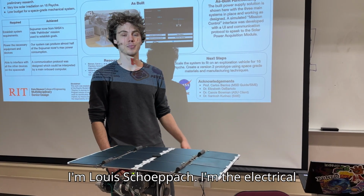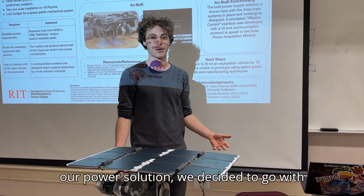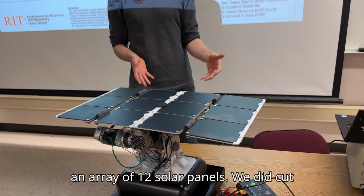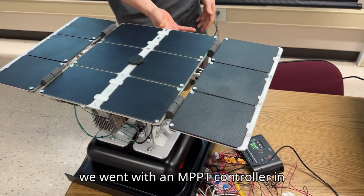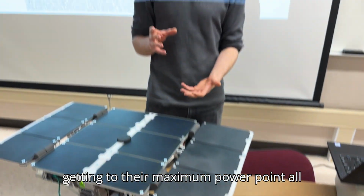Hi, I'm Schoeppach. I'm the electrical engineer on Psyche Mission 2. For our power solution, we decided to go with an array of 12 solar panels. We did cut that down to 6 for budgetary reasons. So in order to support that panel array, we went with an MPPT controller in order to make sure the solar panels are getting to their maximum power point all the time.